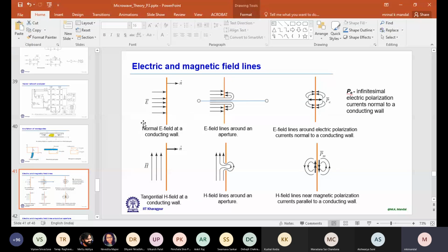Any one of you can unmute and answer. PMC. Yes, you remember it, because the electric field is becoming perfectly tangential. Since it is a PMC, it is called even mode excitation, even though it's just a slot. We may also have odd mode excitation that was not shown. Maybe I can show it in short. Okay, let me share better.